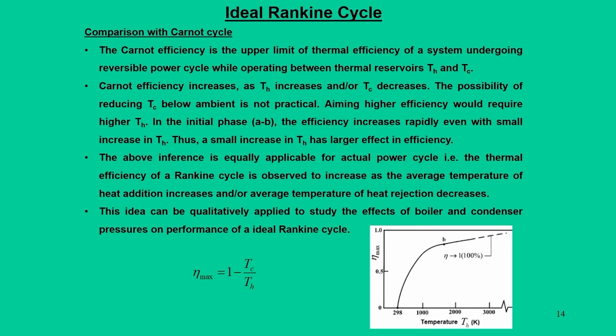Now, let us move on to the thermodynamic angle of the Carnot cycle. In a Carnot cycle we cannot play with the operating pressures, because if you look at the efficiency term, the efficiency of the Carnot cycle is 1 minus Tc by Th. Tc stands for the lower temperature, Th is the higher temperature. So, efficiency can be increased in two ways, by increasing Th or by reducing Tc.